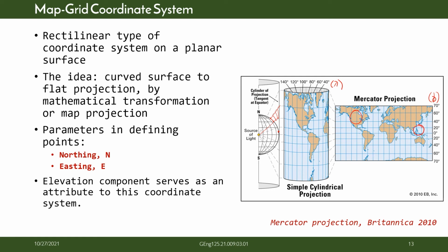From Greenwich, not shown here, somewhere here, where is the Greenwich? This one. So you have your zero longitude. Going east is positive longitude, and going west is negative longitude. So this is your Greenwich meridian. By that, we can also locate your points in two-dimensional space, or in other terms, the northings and eastings.